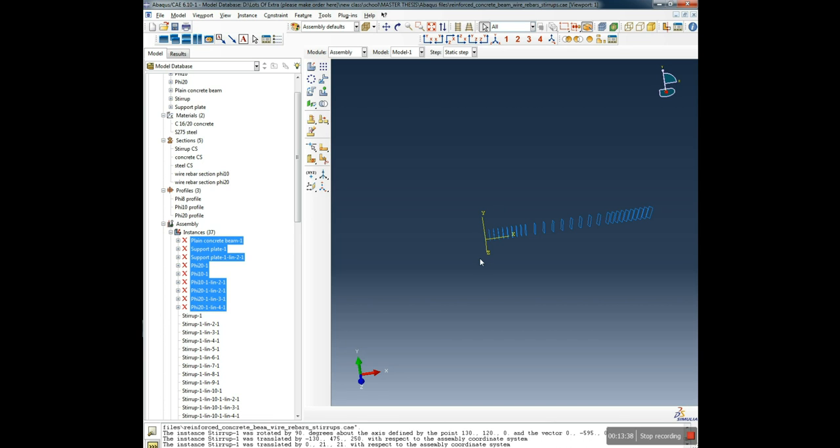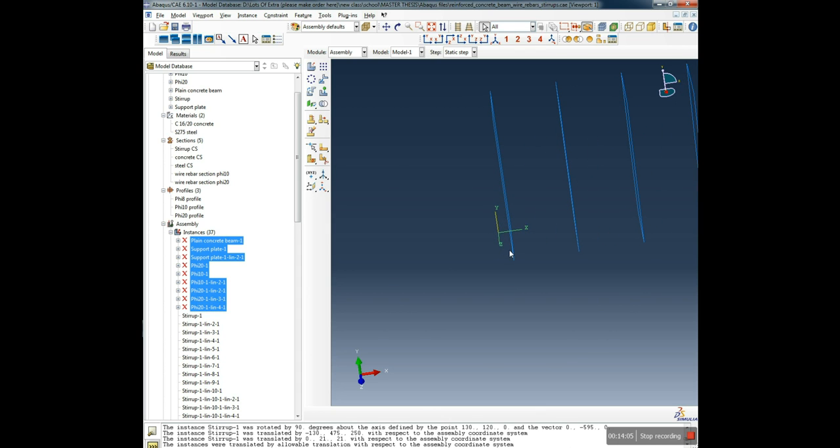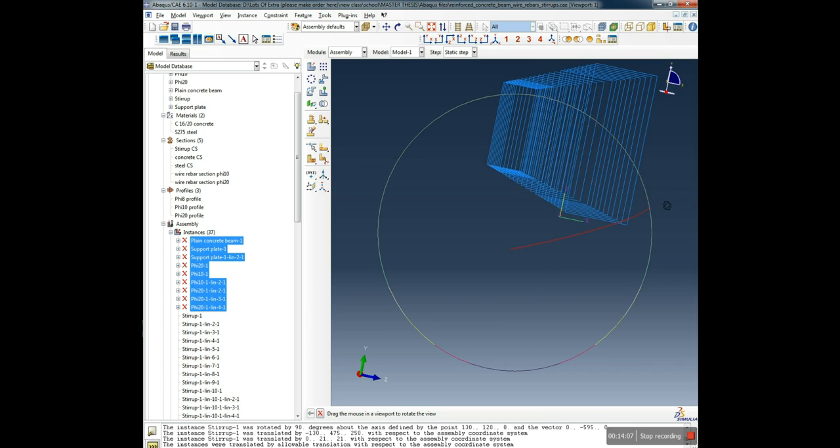So 20 is just the height. So we move it. Yes, so 50 millimeters, everything moves to the right. So translate. Done. Starting point 0, 0, 0. And ending point on x is going to be 50 and the rest of them remain 0. And okay. So now you can see that it's a bit displaced from the center of the system of coordinates.